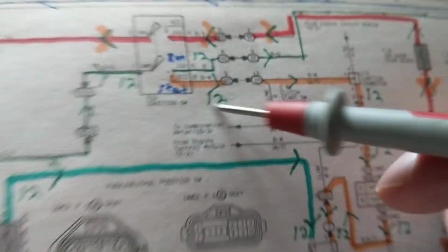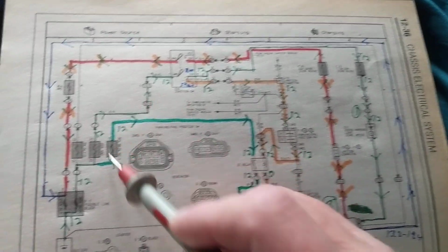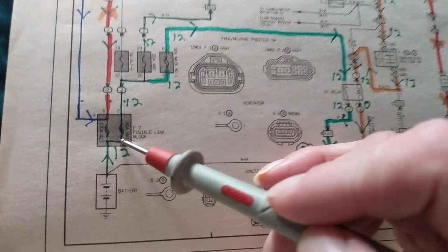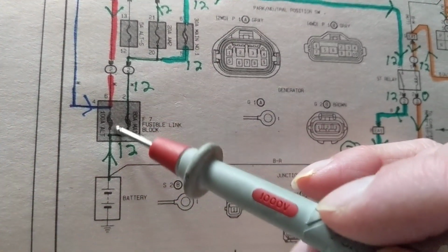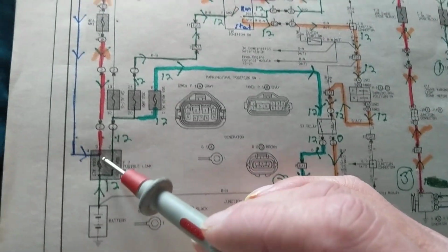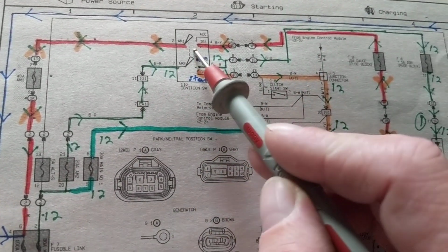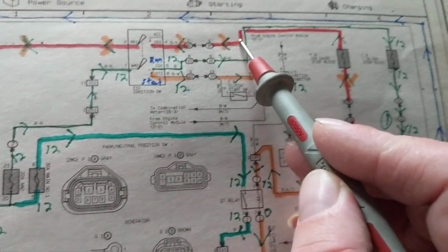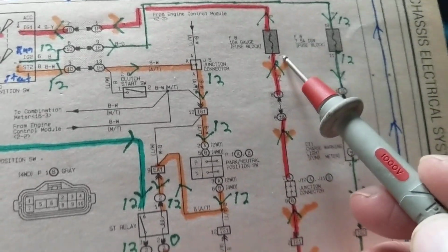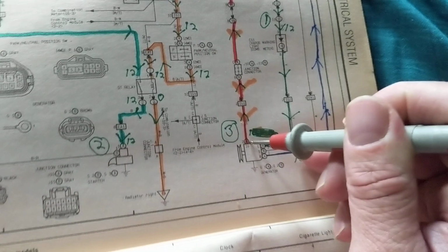Now it's a little different. Where's the connection now? This connection. You see this big 100 amp fusible link in this block? This plays a role in going to another fuse through this ignition switch in ignition 1. Goes through where? Another fuse. It goes to junction, and it goes to the ignition. It goes to